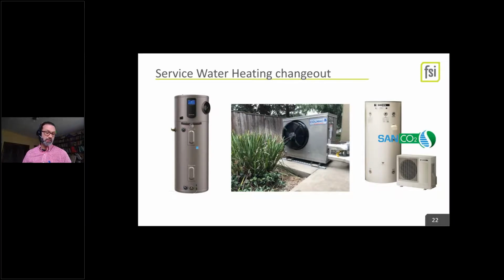Last one, it's basically a CO2 unit. It's a mini split condenser looking box, but it uses CO2 as a refrigerant, and then an indoor tank. So it slowly heats that indoor tank using a trickle heat pump. But because it's CO2, it can go down to super low temperature. The downside is right now it's 1-to-1. We don't have lots of bigger equipment like that. So just like if you were doing split systems in a residential and you got 1-to-1 all over the place and a bunch of rooftop condensers, you'd have the same thing here. We have a bunch of condensers per water heater space. So it's really limited mostly to residential application.